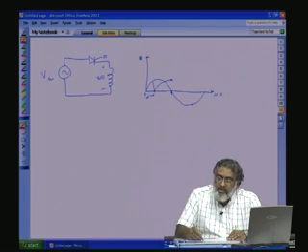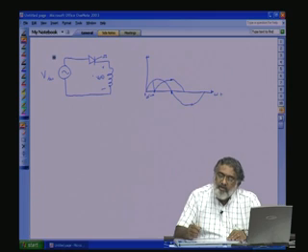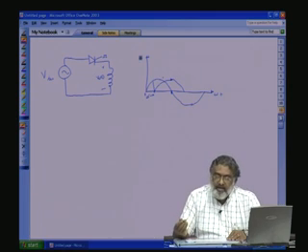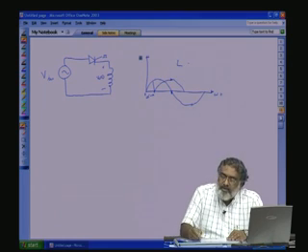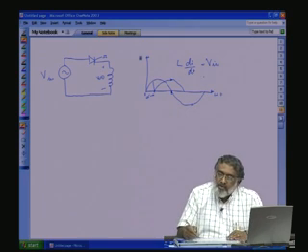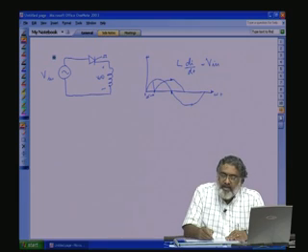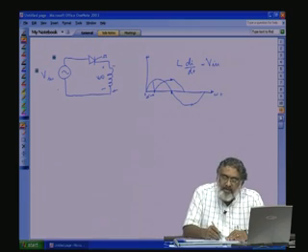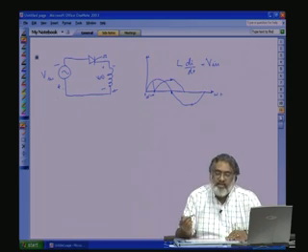So, slowly current will try to decrease from this point onwards. At what point will it come to 0? That depends on the inductance and the initial stored energy, that also depends on the peak value of the current. Now this di by dt is negative. So, L into di by dt is equal to V in, assuming the diode drop is negligible. So, now the di by dt slope is negative from this point to this point. What will happen? The polarity across the inductance will change this way, that is true here also. The AC voltage waveform has reversed. So, Kirchhoff's law will match here also.